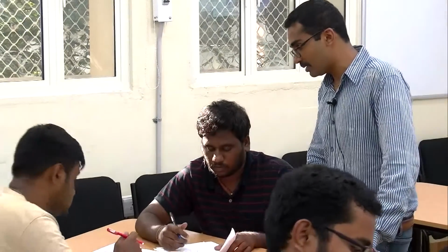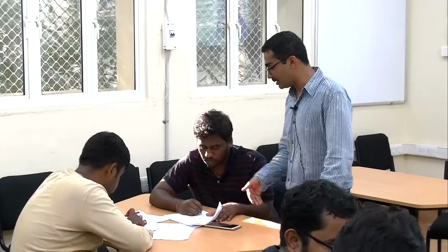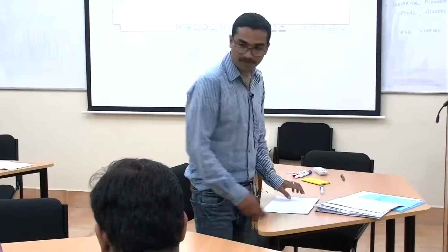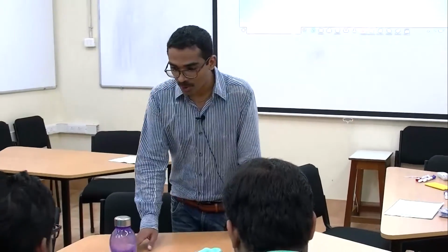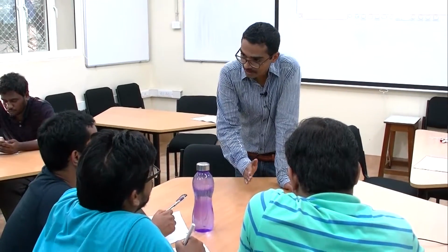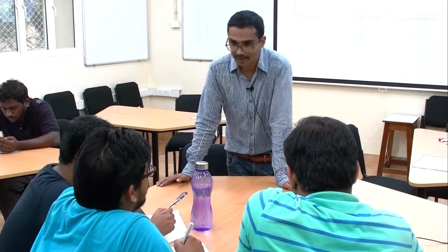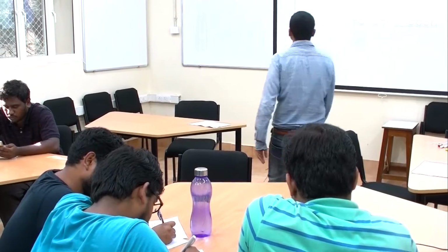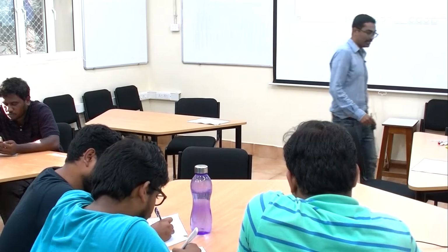So the first question is typical values associated with conductors, semiconductors, insulators, the resistivity values. And the resistivity is inverse of conductivity. Rho is equal to 1 over sigma. Sigma values you have already written down in your notes. You understood the first question? So rho, which is resistivity, is 1 over sigma. Sigma values you know for conductors, semiconductors, insulators. So what are the rho values? That's the first question. And you will give me those values. Okay.